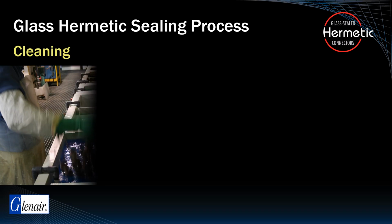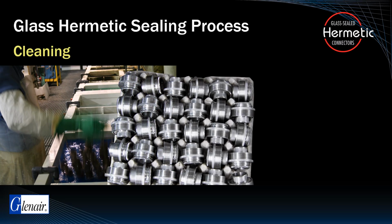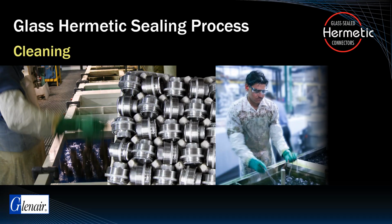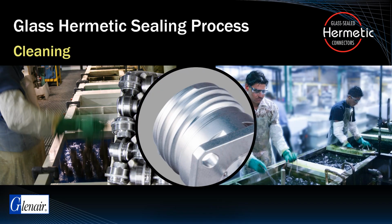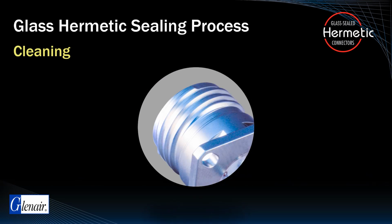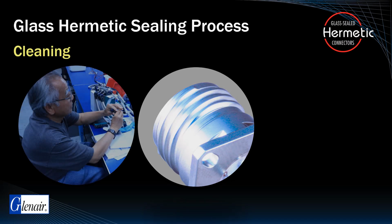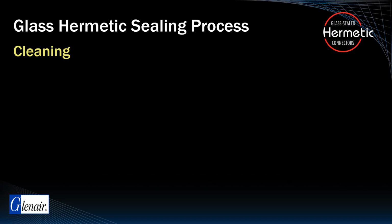Next, the in-process assemblies are suspended with wiring on racks based on their size and configuration and run through a series of cleaning and descaling processes designed to remove oil, oxidation, and other impurities. Following cleaning, the work goes through a bright dip process, also known as passivation, to arrest any additional oxidation of the metal parts. In-process inspection takes place and the parts move on to the next step in the process.